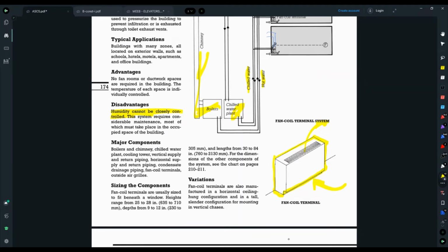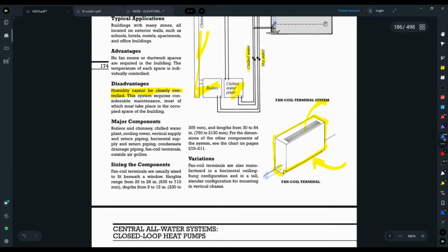So all that the condensate drain pipe really is, is because water will often drip off of the pipes, the condenser pipes. You just need a way to get that out of the space. You don't want mold. You don't want any kind of bacterial growth to result from condensate. That's often how you get Legionnaires' disease, which was an issue in New York a couple of years ago. I think it was roughly 2005 or so, 2010 maybe.